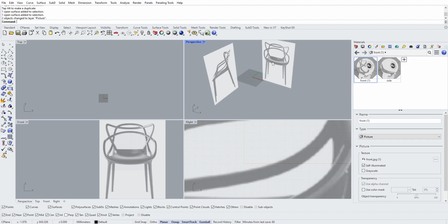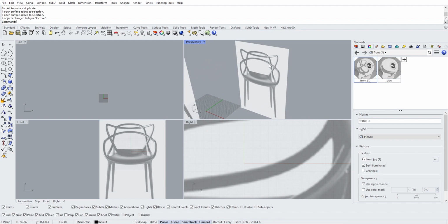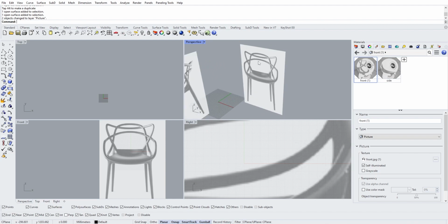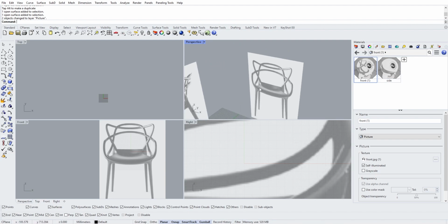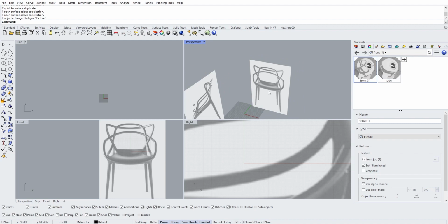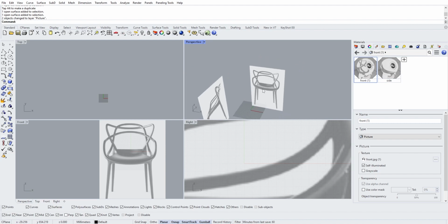So we're going to do the chair in 3 different steps. The first one will be to recreate the curve of the backrest and the armrest here. And out of those curves, we're going to create the curves from the seats that are supposed to follow those curves also. And after we've done this, we will be able to solidify everything with sub-D tools.